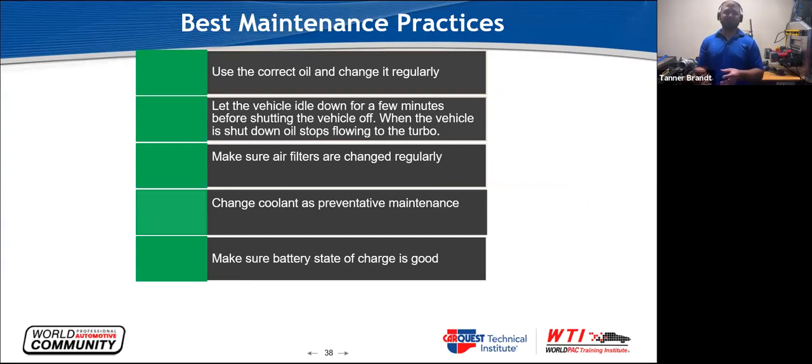As you are replacing turbos, there's a couple things I want you to think about, for your customers, for yourself, for the vehicle, whoever it is. If you're servicing turbo vehicles, whether it be a Volkswagen, a BMW, a Chevy, a Toyota, it doesn't matter. The biggest thing is using the correct oil and then changing it on time.